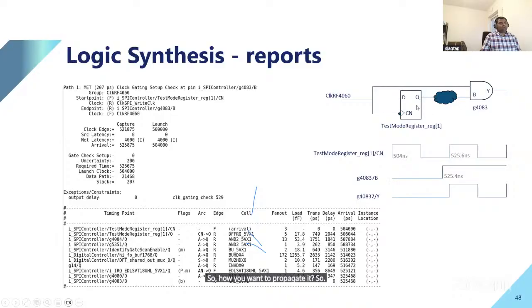So you want to enable that clock gate when the clock is low, so that when the next clock propagation starts, it will be a clean clock propagation you see here at the Y pin. You don't see the distortion. Distortion in the sense, what will happen if the B pin goes high somewhere in the middle here, where my cursor is.